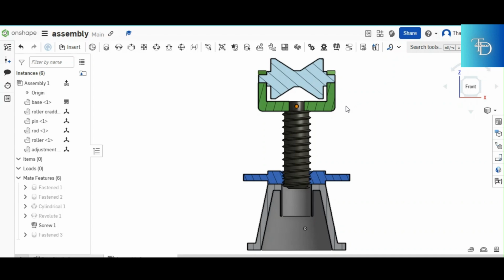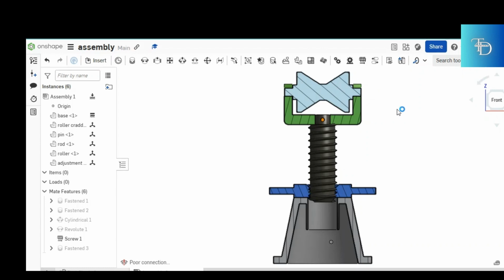The direction of the hatching lines from the cradle are different from the hatching lines of the roller itself. So two parts coming in contact, the hatching lines change direction. That is how you should section your assembly each and every time. On each and every case, do not make the mistake of putting sectioning lines that go in the same direction all the way through the part. That is a mistake. You're gonna lose points with that. If you encounter a different part, you change the direction.